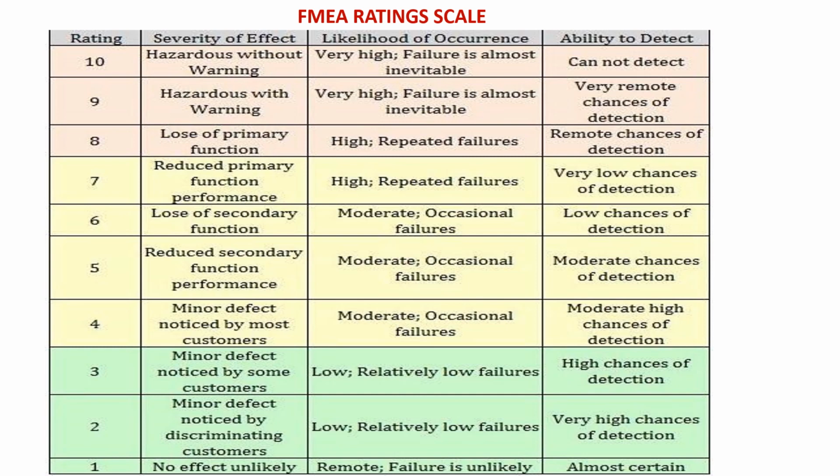failure mode. The risk priority number is a factor which is a multiplication of the severity number, the occurrence number, and the detection number. It will always be between 1 to 1,000, and the lower the number, the lower the risk. The higher the RPN number, the higher the risk.